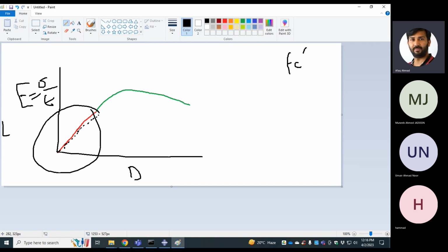And then plot your load deflection curve from Abaqus, which is marked as red, and the dotted line, the experimental. If your FEM behavior is following the path of your experimental behavior, that means you're on the right track. But if this is not on the right track, let's assume your experimental is orange and your FEM result is the red one. That means you have to play with your material properties.